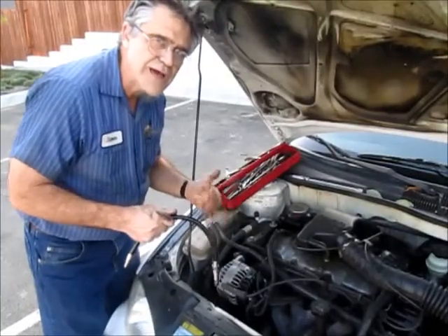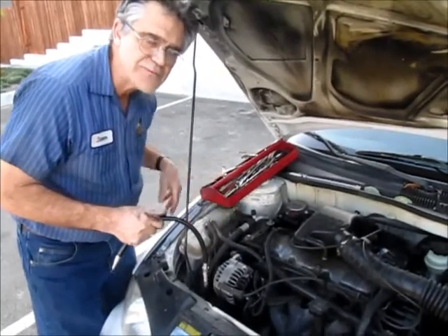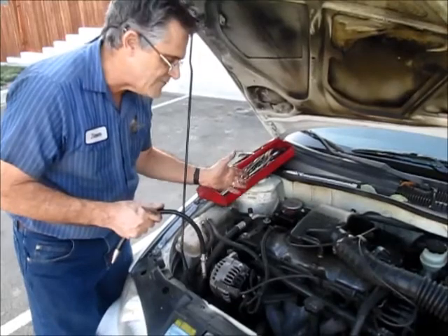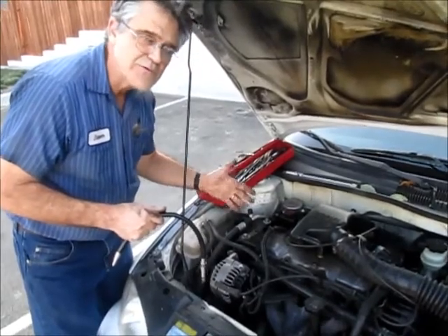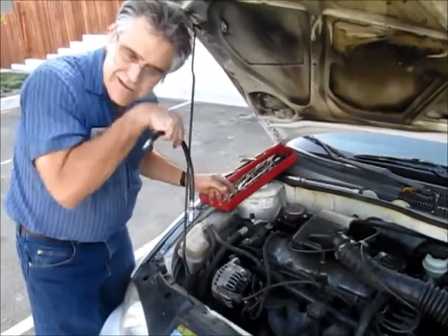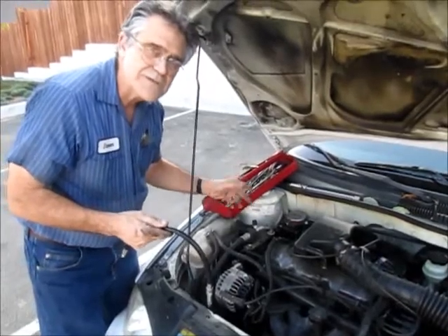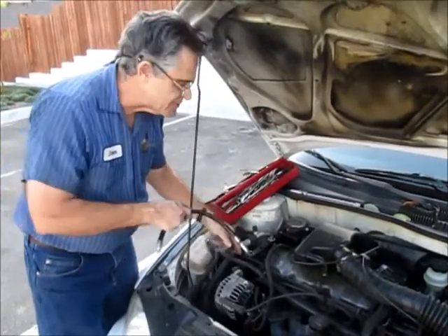I don't believe this spark plug is bad, but we may have a compression problem. So let's check that next. You want to verify that you don't have a major engine problem. If you have a compression problem, then we might have a bad valve, etc. So we don't really need to check injectors and all that yet, because if we have a compression problem, then you found the problem immediately. So we're going to do that first really quick here.